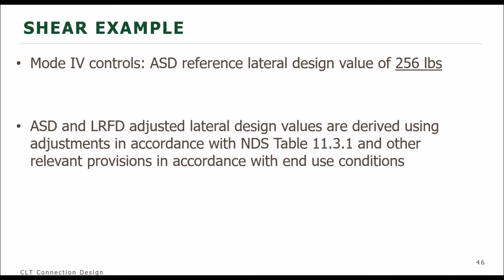And as always, these are, again, the unadjusted design values. If you are going to use adjusted design values, you need to provide those adjustments in accordance with the NDS Table 11.3.1 design values based on your end conditions.